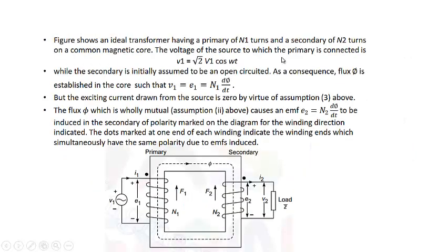That I just told you, that whenever the current flows over here, it produces flux in such a way that it opposes it. When current flows here, you will see that this flux will be reduced. When this flux reduces, you will see that this flux reduces. But as I have told you in the earlier classes, the transformer is a constant flux machine, and if this happens, it may create an imbalance between V1 and E1, and I will tell you how that happens.